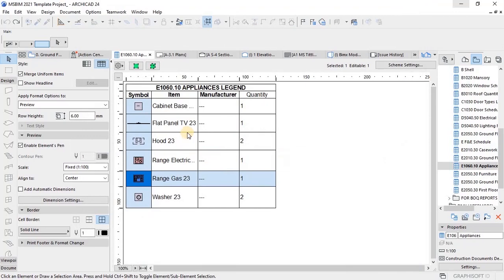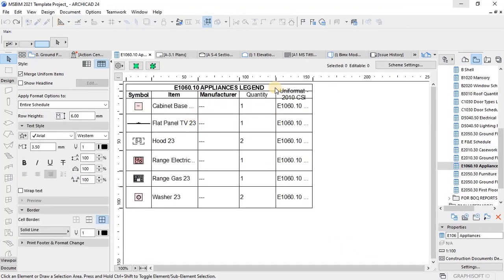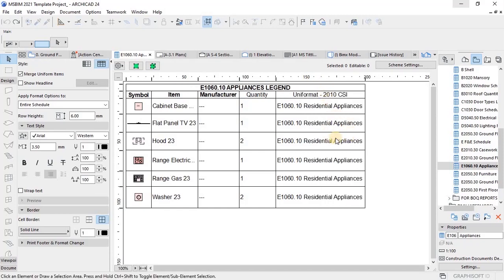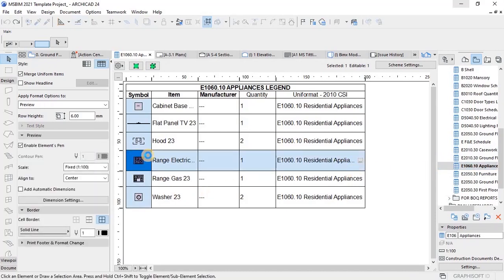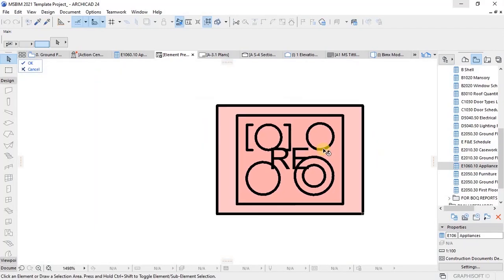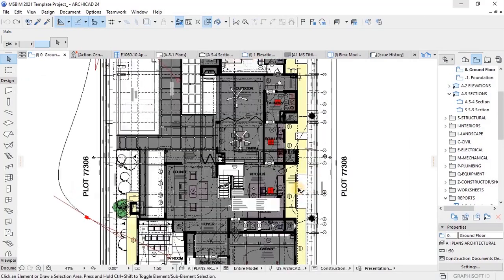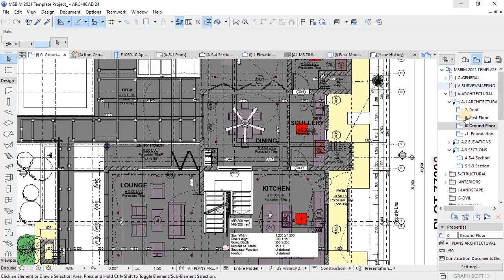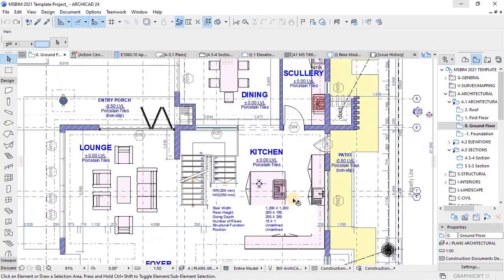We have other video tutorials about creating accurate cost estimates, how you could create and extract quantities of your model from your walls, from anything. You can extract quantities, and then you could tie that with Excel, the reports with Excel. And then we have a full tutorial about that. I'll leave the link of the video to this. And that's 5D BIM.